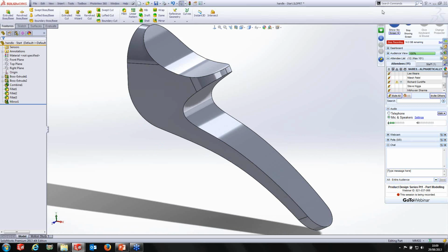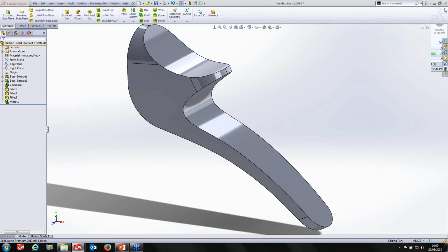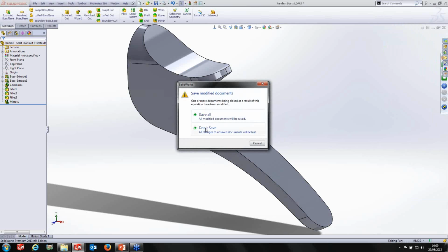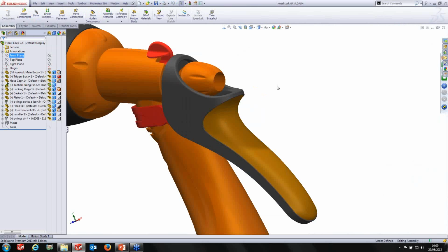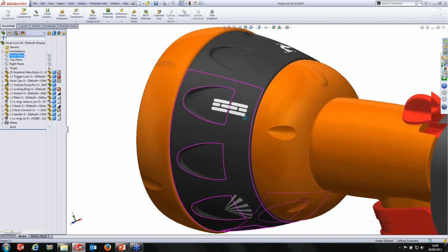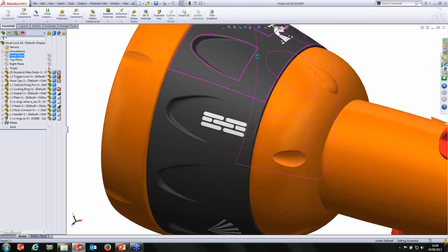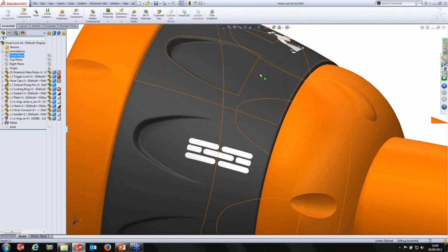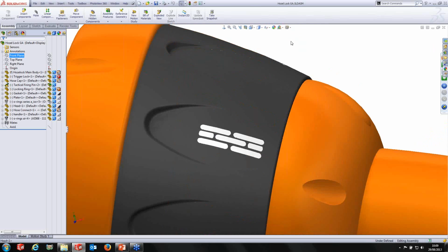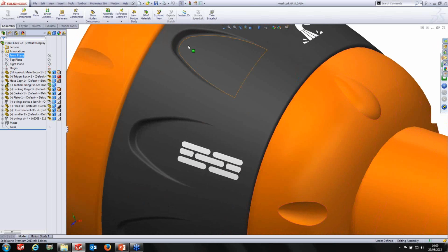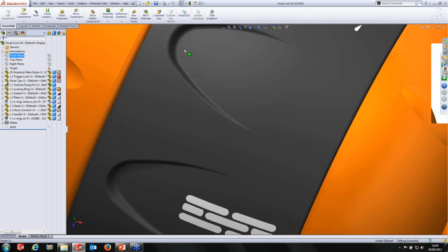Okay, we're now going to move on to another example. Okay, we'll just get rid of that one. So the second example I'm going to have a look at around the top here is the joint between this hole in the head, and the fact that it's tangent on the other side. So you'll see that it's sort of cutting into the model, but it has a nice tangent joint at this position. It's not a nice smooth joint between the two. We've also got it so that it is slightly drafted on this face just here as well.